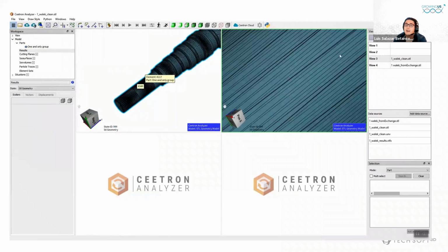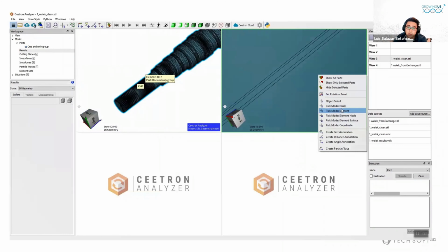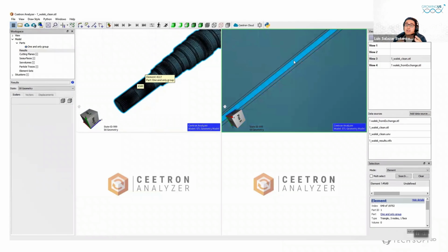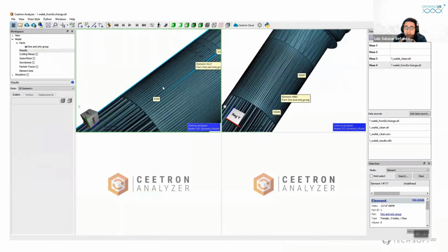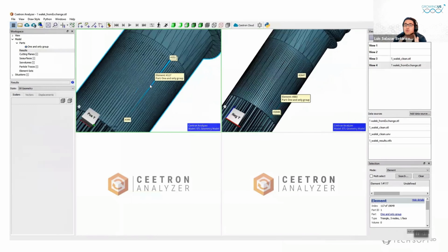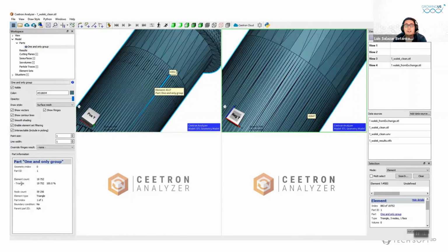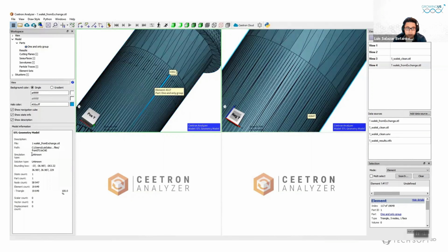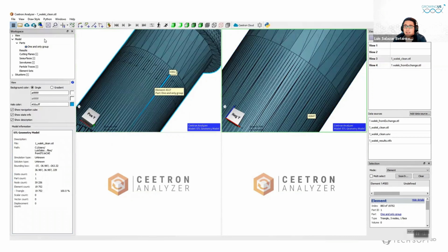I am showing here now the clean STL file from Polygonica. Even though Polygonica has now exported a valid tessellation, and the model is well enclosed, we notice a little detail that this tessellation is too large, which means that the quality of the triangles is not adequate or appropriate to make a finite element simulation. But we can see also that the triangulation has almost 2,000 triangles, and of course we will use that as an input.